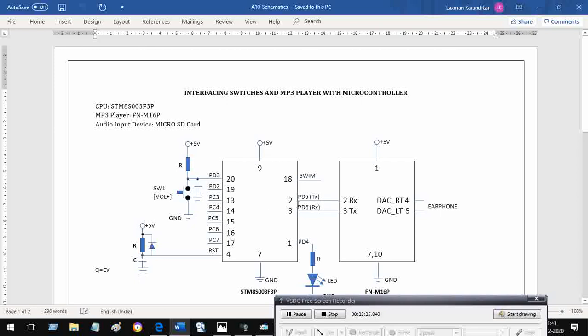What I'm going to send is that 0x41 along this, but I'm not sending it to another device. I say come back and enter the RX pin. This is what I have done. I shorted these two pins together. So whatever comes out of pin 2 will enter pin 3. So there will be a receive interrupt. This is how we are generating the receive interrupt.